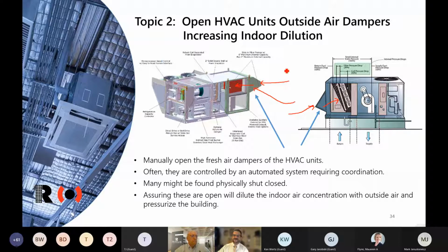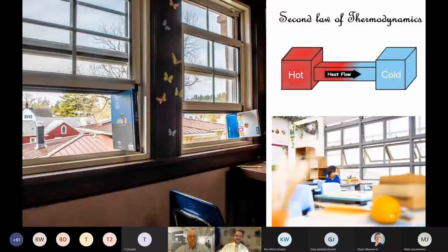Many years ago, a lot of these were shut down for energy efficiency, just to save energy. If it's too cold out, the heat's going to run constantly by bringing in colder air, and that's another penalty of opening these up. And the penalty can be pretty steep in some cases. You're intentionally bringing in colder air, you're filtering it, and then you have to reheat it to make the area comfortable. And it's the same penalty with opening windows, by the way.